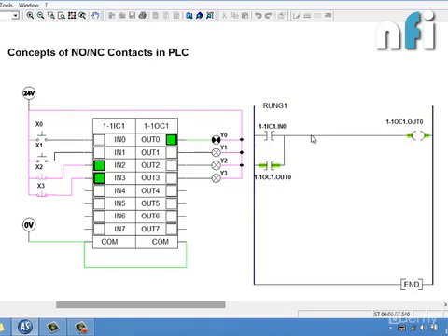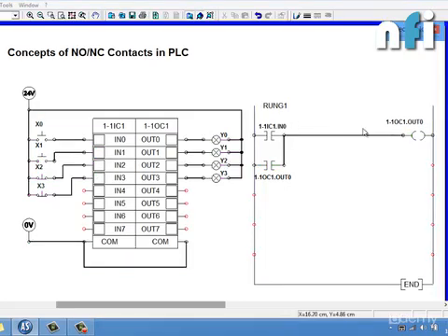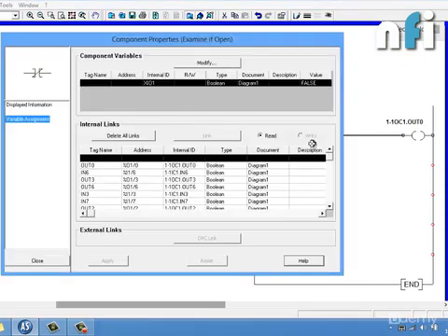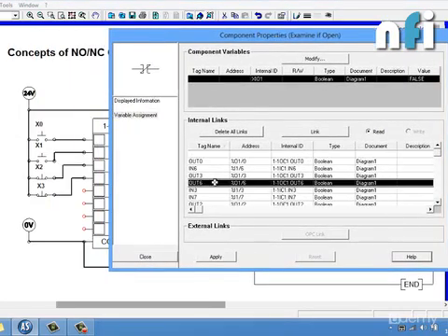Now I want to stop this latching, I want to unlatch this circuit using NO switches, using this switch. How can that be done? You can see that this switch is used to actuate IN1. So to turn off this output coil, I have to introduce the NC of this IN1. Okay, so let's see what will happen. Let me connect that. This comes here, this will go here, and I'll give it a tag of IN1 like this.